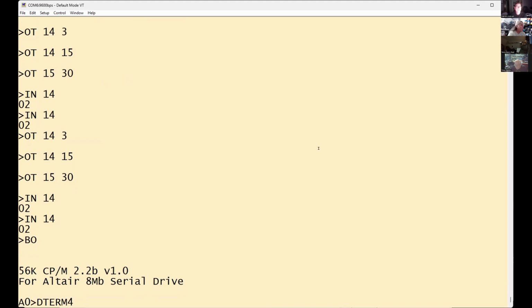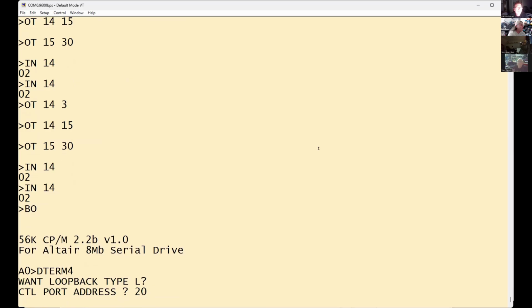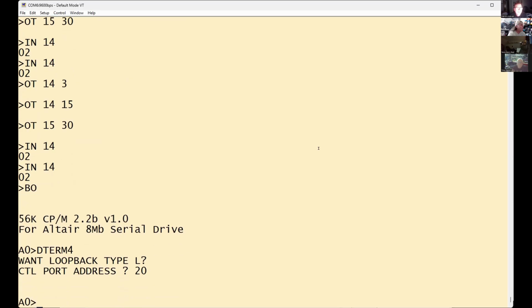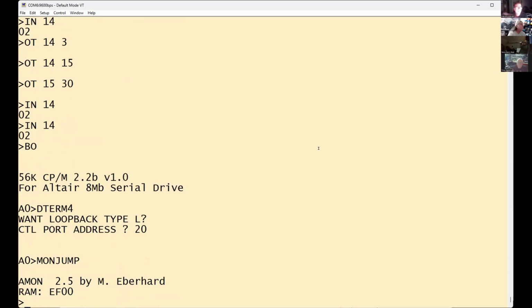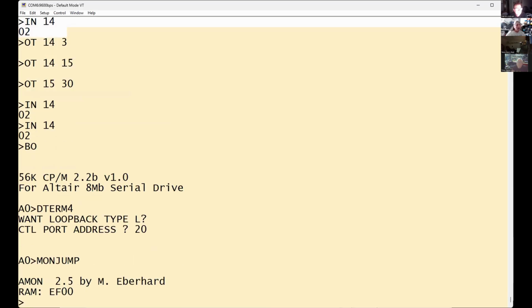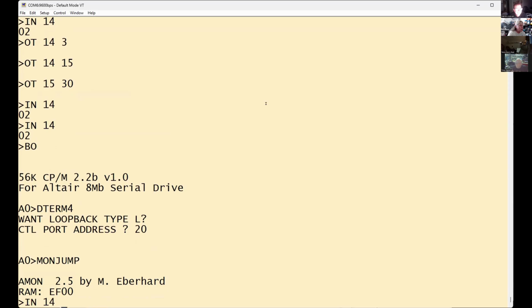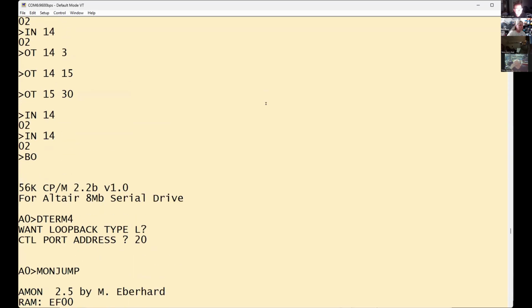Because if you type a character, like I said, if you run my front panel test thing and you single step to an IN instruction on port 14 and you type a character on Tera Term, that LED is going to come on. You can be not running any programs, probably not have RAM in your computer, and that light will come on. Well, you have to have RAM to run the IN, but yeah. I'm going to put these things on a note there. So it looks to me like the UART isn't even seeing the data you're receiving. So that's either a cable, something.